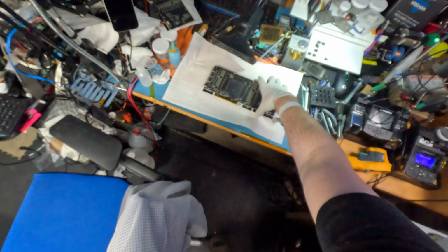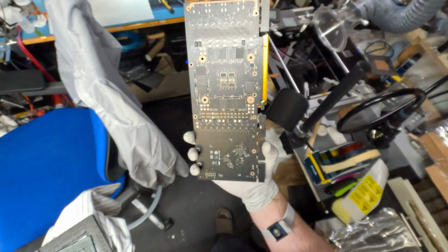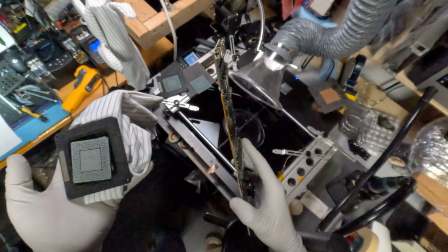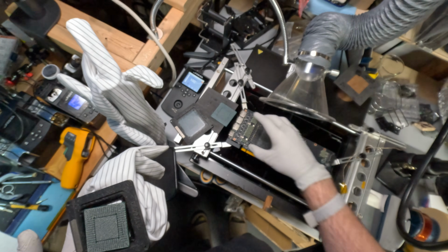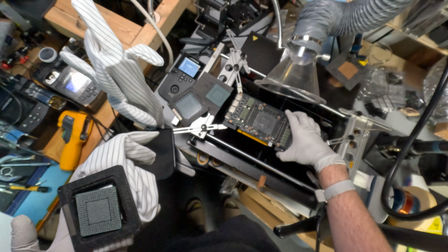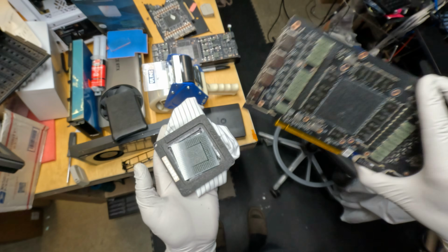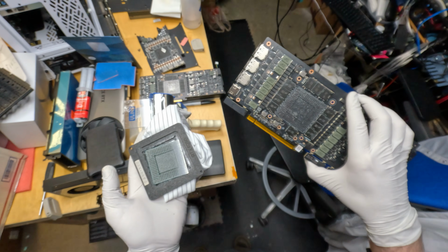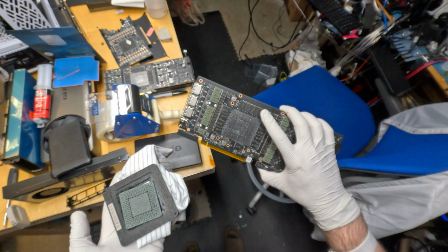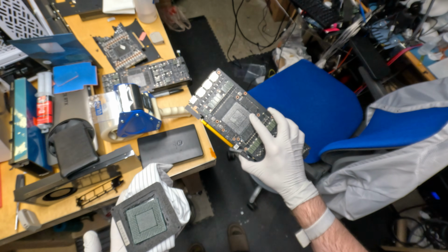So what I have here is a board that I had ready for another conversion, and so this has known good memory and known good donor memory, and one of these cores was going to go on it. But before I do that, I'm going to quickly put solder on this core that came from the card that is having those issues over 24 gigs, but it's fine on Windows for some reason. So I'm going to solder it to this board and then see if those issues persist on comfyUI.